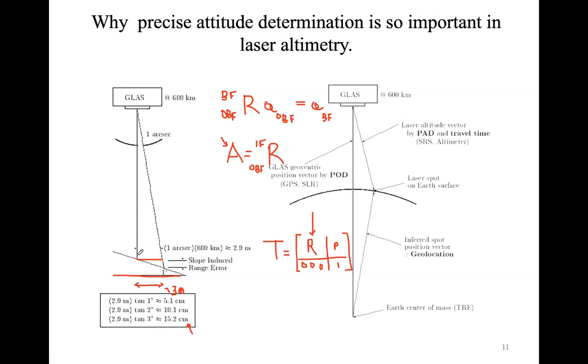On those regions, if you have a requirement on the attitude matrix, so that you need to know the attitude with an accuracy of 1 arcsecond, it means that your instrument is going to see errors given by the attitude, because the accuracy of the measure of the instrument is lower than the errors introduced by the attitude.